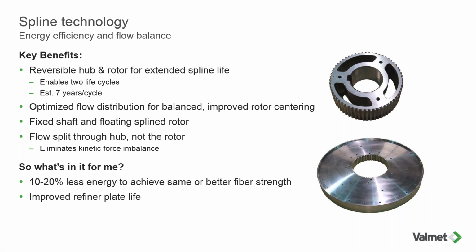So we're looking at better pulp at higher freeness going out of your refiner. You're applying less energy, so you're dropping the freeness less. And because now the rotor is perfectly balanced, whereas before there were all those mechanical issues associated with it potentially balancing itself, you're getting the same plate wear on both the stator and rotors, meaning on the door side and on the motor side. So plate life is substantially improved as well.